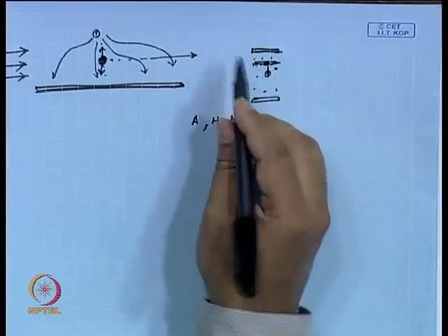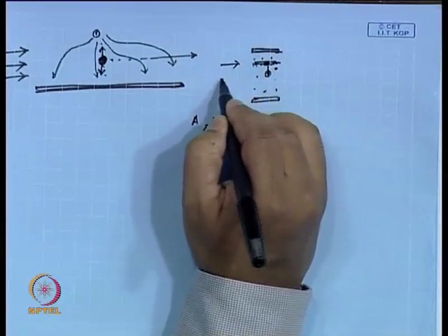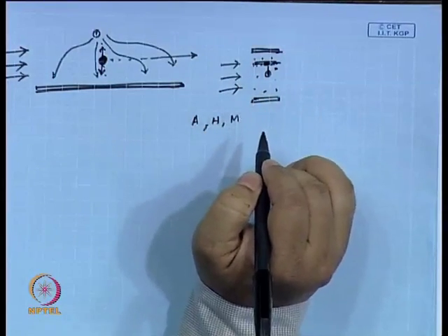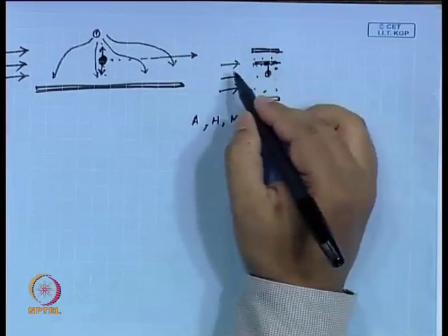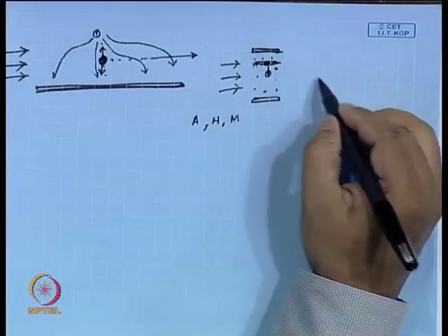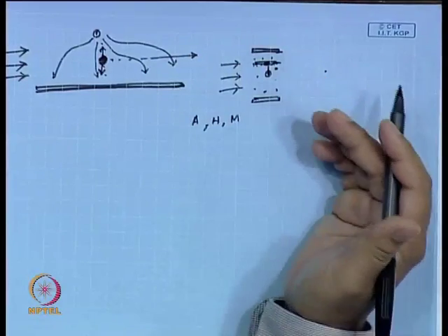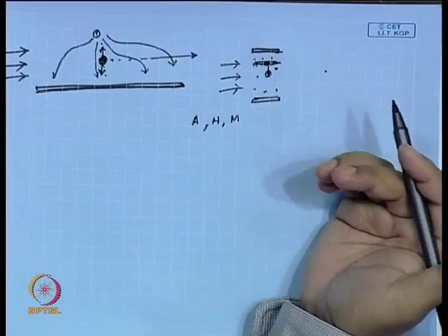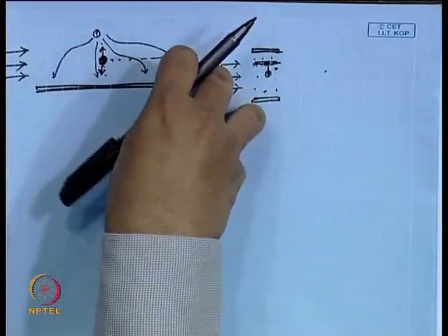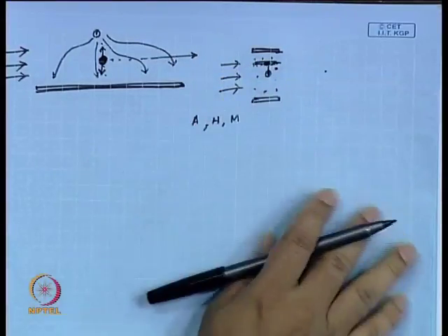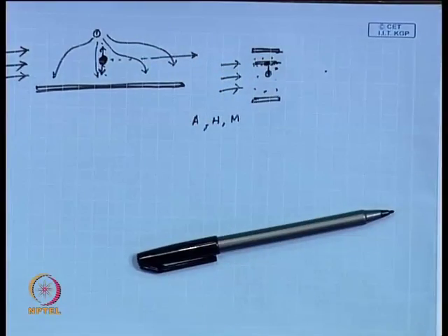On top of it, if you apply a laminar or parabolic velocity profile through this, then at the outlet you will be eluting one layer at a time, first the central layer, then the other layers. If you have a pre-calibration done, that means if you had a known sample going in and you know when the components are eluting, then by looking at that calibration plot, you can compare with a real life sample and say that this real life sample must be having these components.